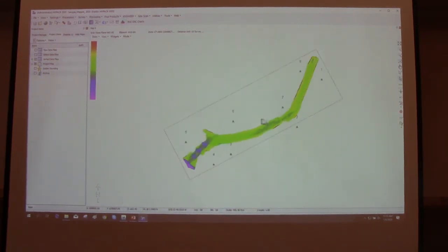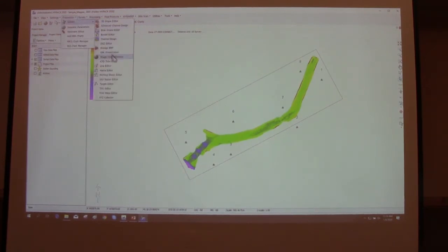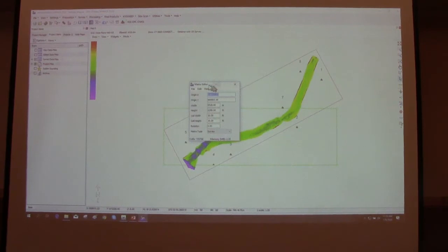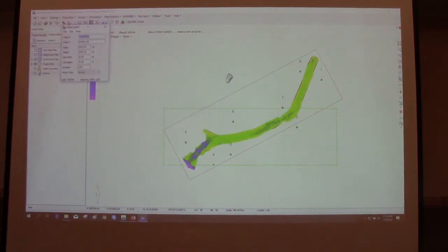Okay, so first thing you have to do is create a matrix file, and that's under the Preparation, Editors, Matrix Editor. I have one drawn on the screen here, but this works very similar to the plotting sheet editor, where you get a rectangle on the screen. You take the lower left-hand corner, position it, rotate with the opposite, and then you can use the other ends, the opposite ends, to change the length and width. And you see those changing in the box, as we see over here.